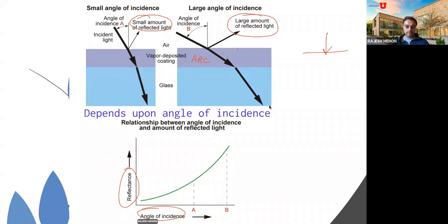Whereas the angle increases, of course, the reflectance increases. So you're losing more and more light. Okay. Difficult problem to solve, by the way, which is another reason why you track the sun, right? Track the solar panel. In other words, if you have the sun and the solar panel straight down, that's perfect. This is the ideal situation.